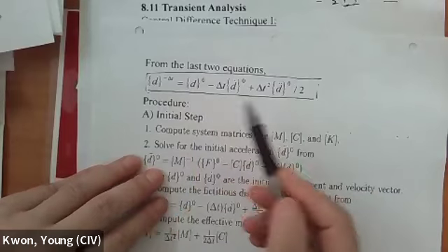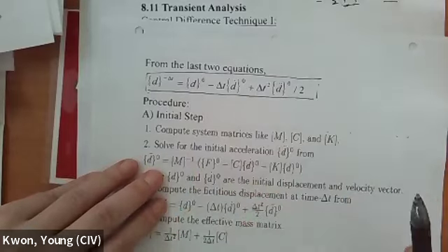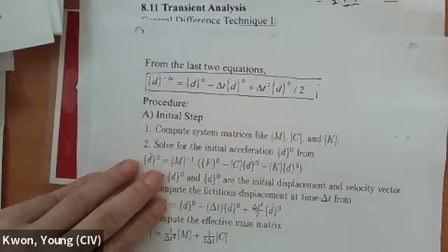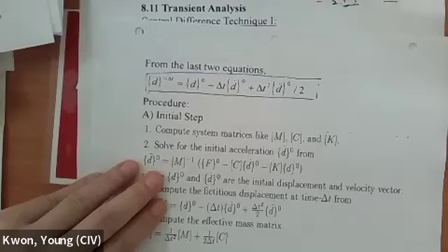All right? In a time-dependent problem, one of the natures is that the solution at the previous time is going to affect the solution in the future. So whatever wrong input you put in at the beginning is going to scrap the whole solution after that. That's the nature of a transient solution. So you have to start with the right solution.